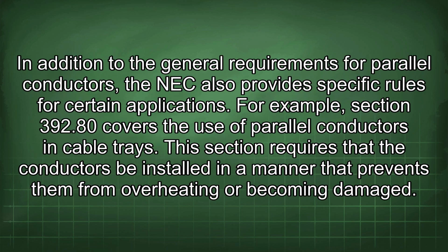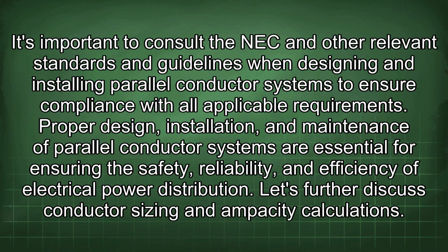In addition to the general requirements for parallel conductors, the NEC also provides specific rules for certain applications. For example, Section 392.80 covers the use of parallel conductors in cable trays. This section requires that the conductors be installed in a manner that prevents them from overheating or becoming damaged. It's important to consult the NEC and other relevant standards and guidelines when designing and installing parallel conductor systems to ensure compliance with all applicable requirements.